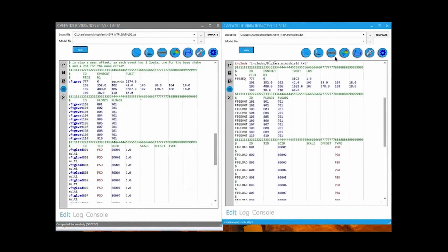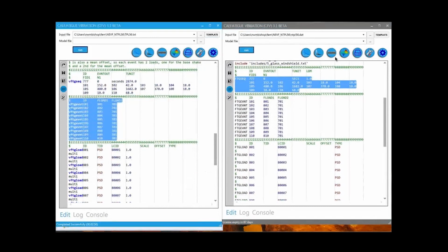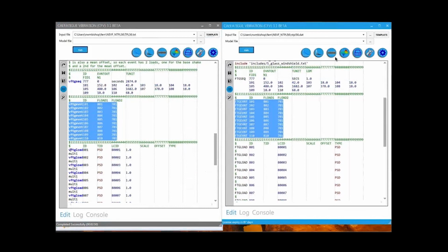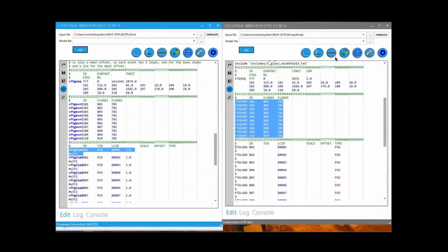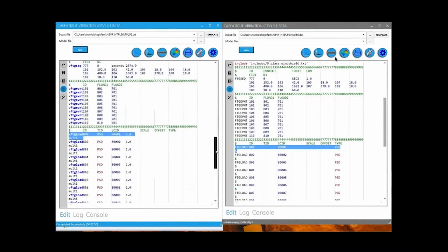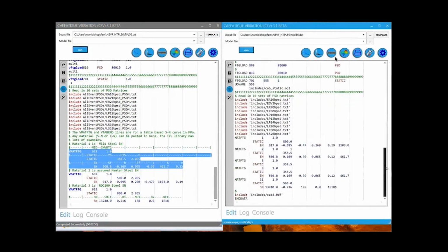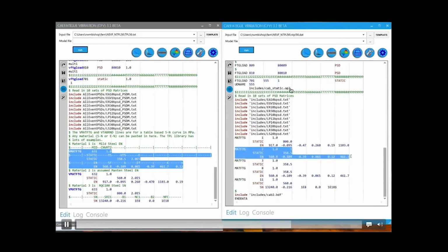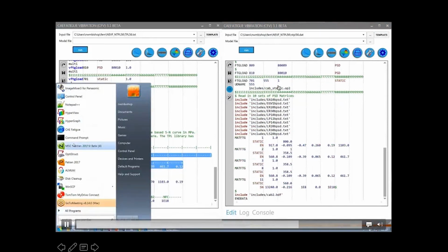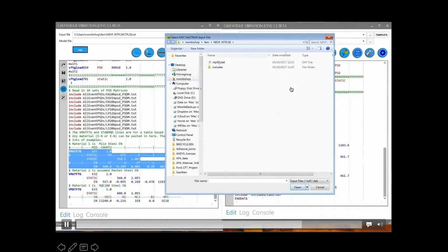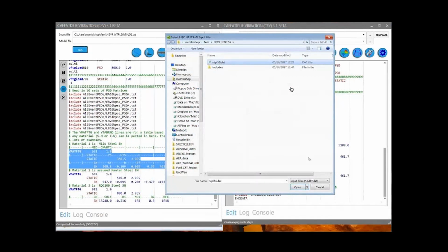Now, you're going to have to add into this, because it's got to be a file capable of running a Nastran job. You're going to have to read in the Nastran part of this, which is the model, the subcases, the case control. So you need to have all of that available, and you need to read that in. So you'll see various includes here, where those are read in. You'll see the loads there. So these are essentially identical fatigue setups, with the Nastran form on the right having, in addition, the includes to provide the model. So you see include cap static. That's where, in fact, that's where the model is read in, and that's got a typo there because it's not OP2, it's PDF. So now we can go ahead and run that with Nastran.